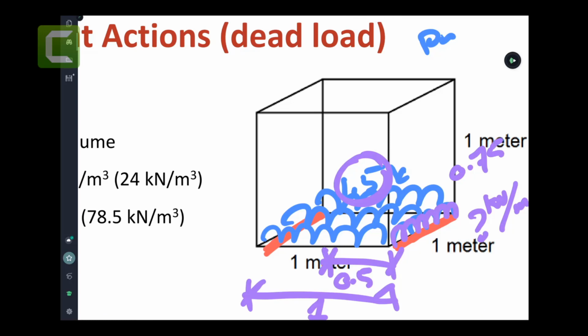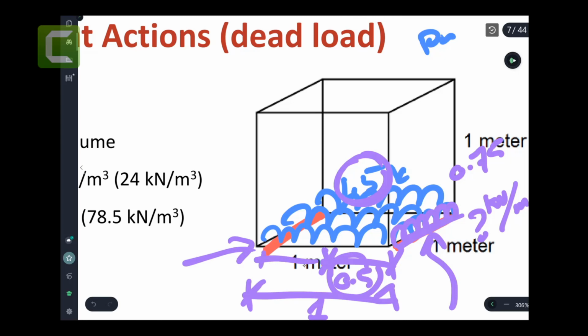Okay. We call 0.5 the floor load width or roof load width, whatever we're designing. If we're designing a floor, we call it floor load width. It means what distance does the supporting member carry? Now this side is carrying half of the floor and the other side is carrying the other half. So you're only going to take 0.5 coming onto this right-hand side, right? So mathematically, what does that mean? You have to multiply 1.5 by 0.5.